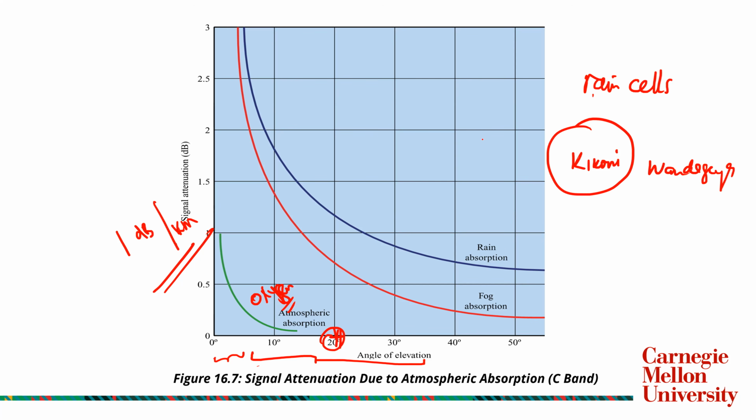So if I have my signal from, maybe this is Kasubi, and maybe this is Kororo, and I have my antenna going through the rain cell to Kororo, maybe a terrestrial link, I'm only concerned about this distance. This is the distance over which I apply my rain absorption. I don't apply rain absorption across the whole link because clearly the whole link is not inside the rain cell.